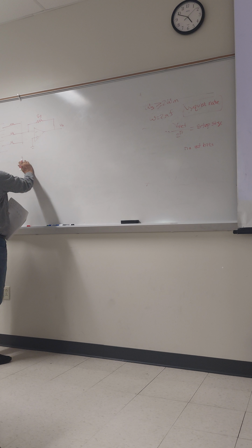And then we also discussed the full scale output voltage, FSO. The equation was 2 to the power n minus 1 times Vref by 2 to the power n. As you can see, this is the resolution, also known as step size, or 1 LSB, everything is the same.